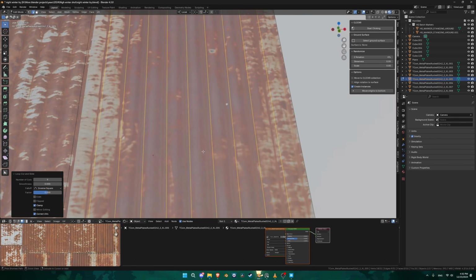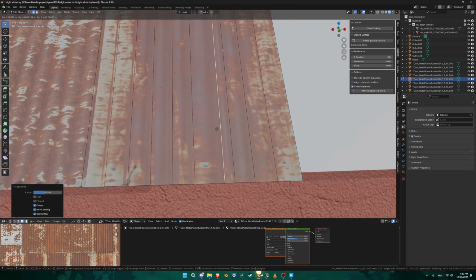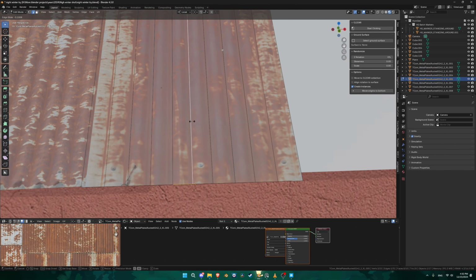To give them a proper 3D look, go into edit mode and add edge loops. Match each edge loop to where the real indent in the image is supposed to be. Then select all of them and press bevel and scroll up to add an extra edge loop in the middle. Then you can just select all of the middle edge loops and pull them down by pressing G. Repeat the same process for the rest of the pieces. Now randomly arrange them to fill the rest of the roof.